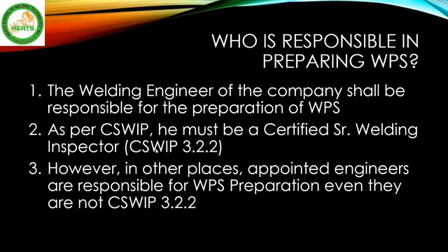Who is responsible for preparing the WPS, by the way? By right, it will be the welding engineer of the company. He is the responsible person in preparing the WPS. However, as per CSWIP, he must be a certified senior welding inspector, or CSWIP 3.2.2. However, in other places, appointed engineers are responsible for WPS preparation, even if they are not CSWIP 3.2.2.